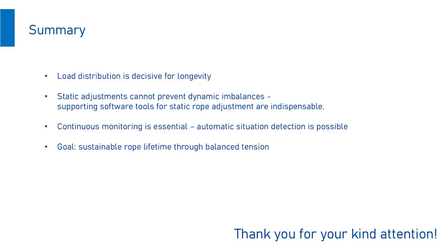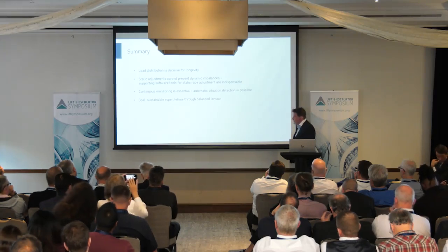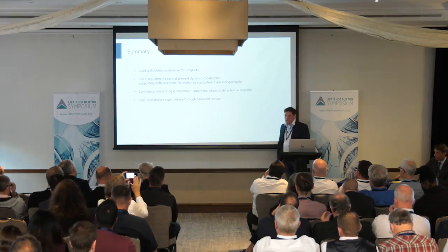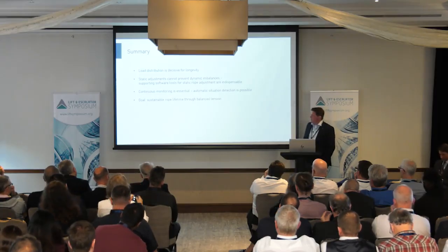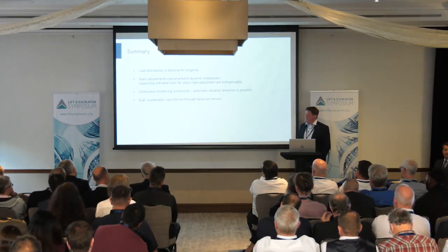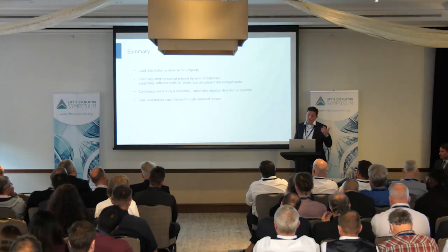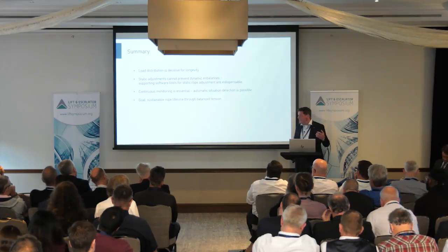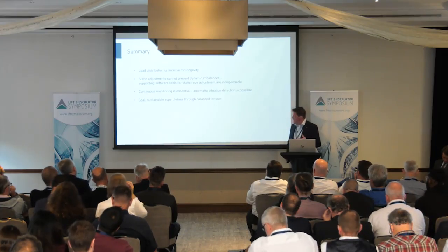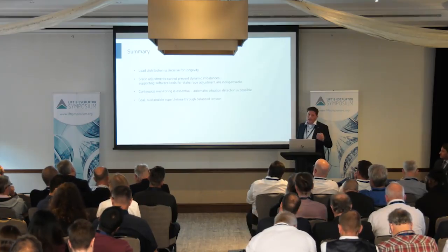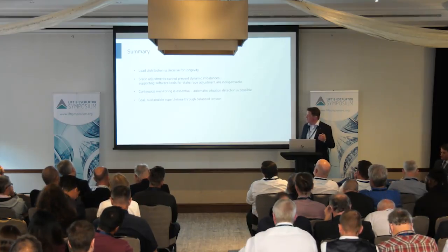And that is what modern IoT devices or even overload controllers already do. They continuously look at these measurements. They continuously cover the rope tensionings during the travel, can detect worn-out grooves. They can detect the beginning of wearing out. They can detect twisted ropes and things like that.